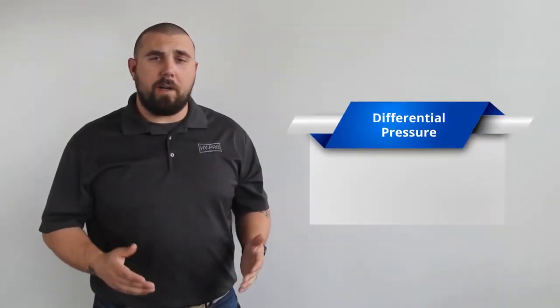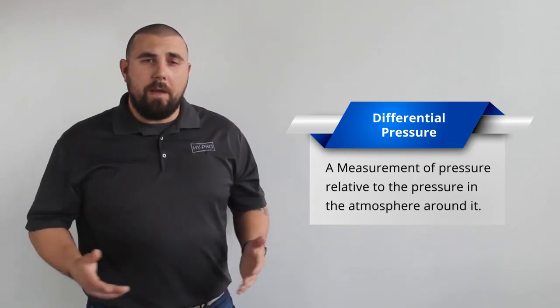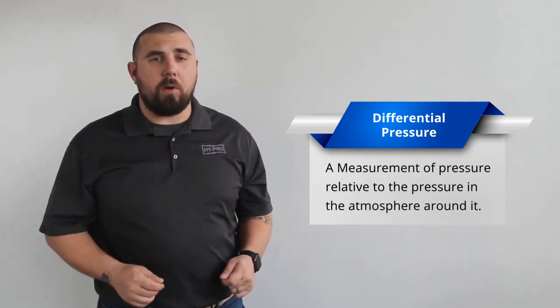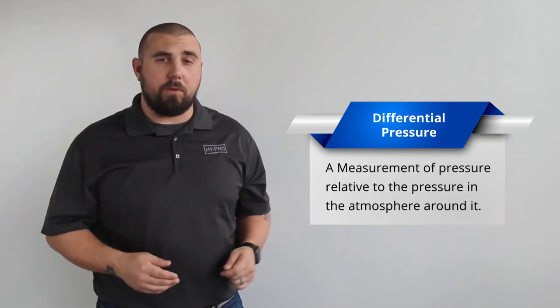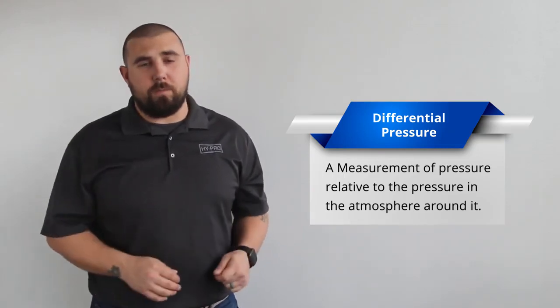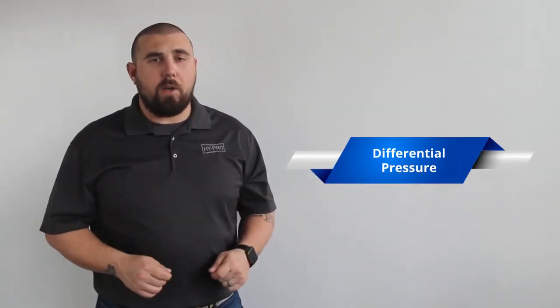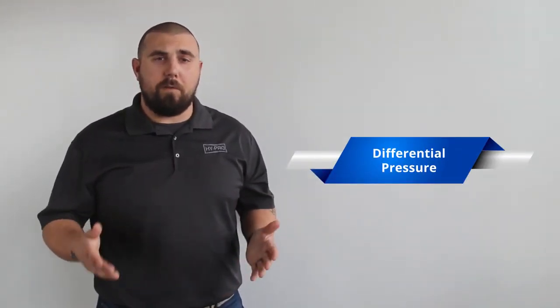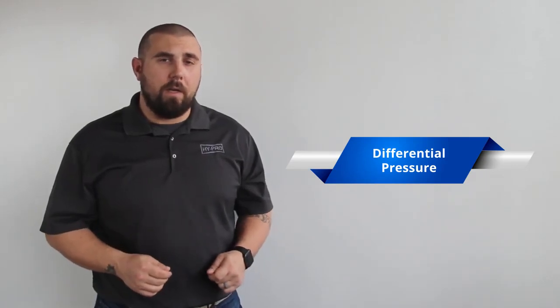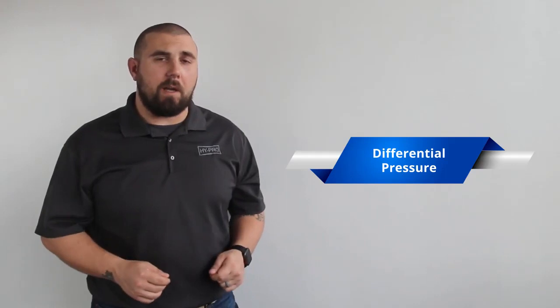Differential pressure is defined as a measurement of pressure relative to the pressure in the atmosphere around it. In this case, differential pressure would be referring to the measurement of pressure within a test filter relative to the pressure surrounding the filter inside of the housing in which it has been installed. Differential pressure is used in the hydraulic and lubrication filter industry to determine how efficiently fluid is moving through a filter. When differential pressure is high, it's a good indication that a filter is close to being at capacity and should be changed.